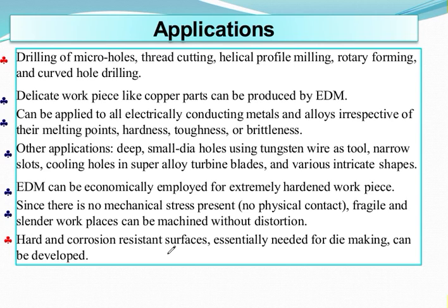EDM can be economically employed for extremely hardened workpieces. Since there is no mechanical stress present, fragile and slender workpieces can be machined without distortion. Hard and corrosion resistant surfaces, essential for die making, can also be developed.